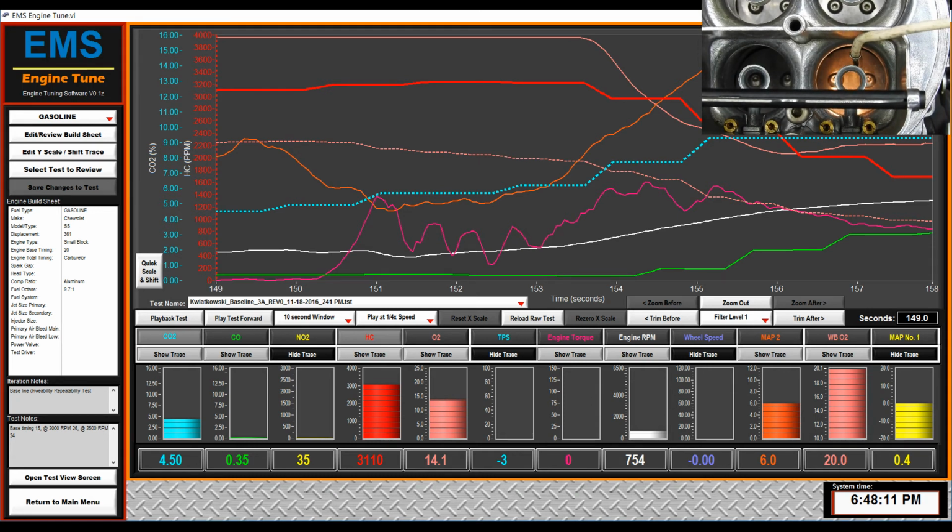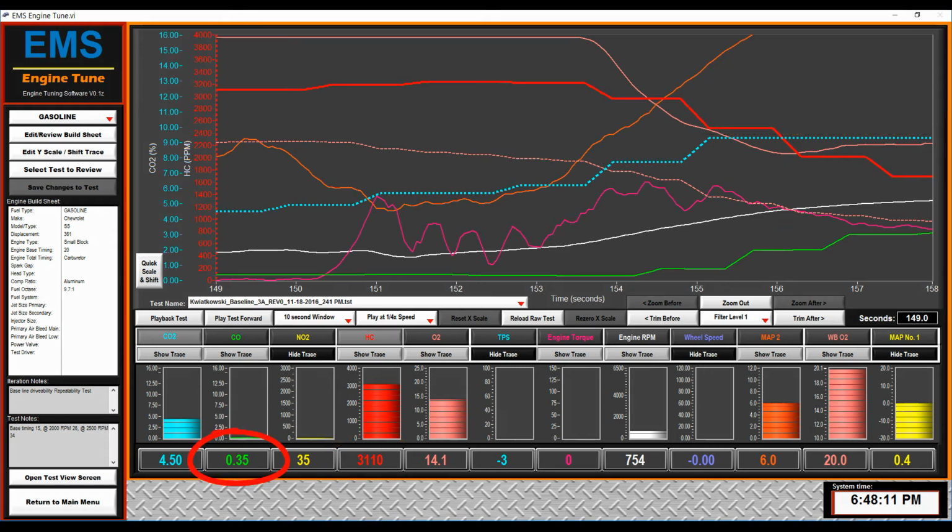This increase in the fuel is going to be reflected in hydrocarbon, not CO, because CO is the effect of the burn. The hydrocarbon is the amount of fuel being metered into the engine. Because of the overlap, we are going to have more hydrocarbon in the exhaust. This is the total of the wasted fuel that went unburnt through the engine. The combination of CO and hydrocarbon is the total fuel that the carburetor was metering.